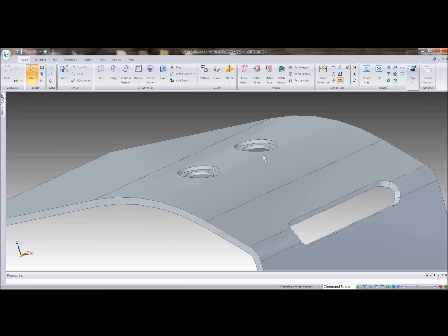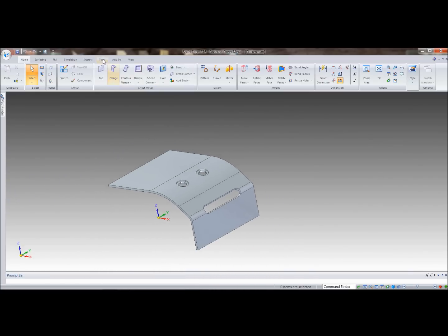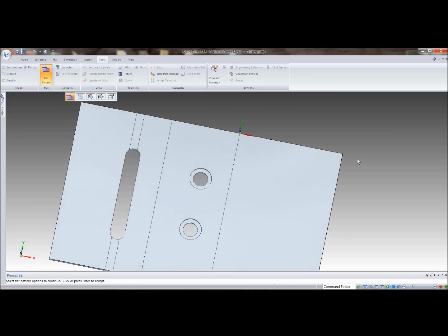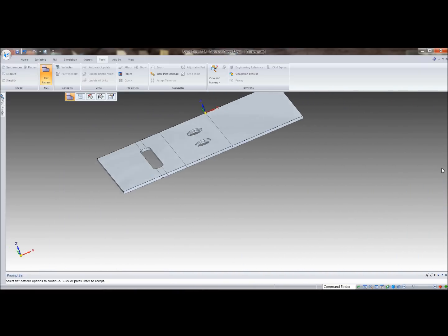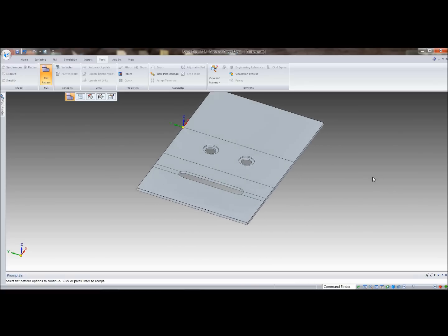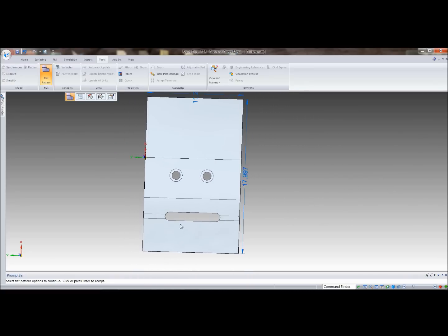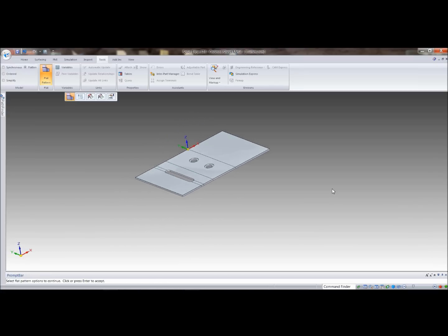But it's representing right now like these holes are represented as curved surfaces, basically, just like you would expect. So when we go ahead and do the flatten pattern, you'll see that it takes everything back to its normal two surfaces, just like you would expect and just like you would need to create your flat sheet metal part. And if I'd have been a little more on the ball, I would have had my little cutout have a little more of a smile to it to indicate that you should be smiling now, because this is a great release of ST6 of Solid Edge.